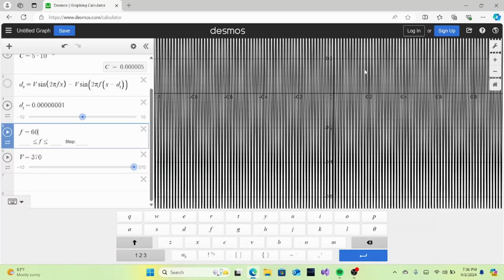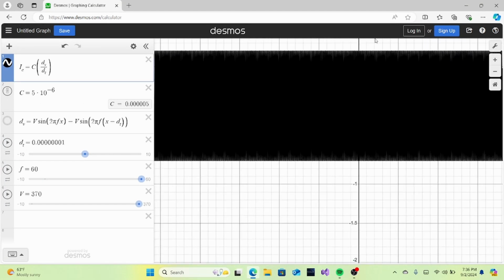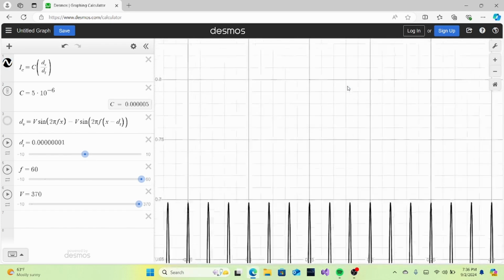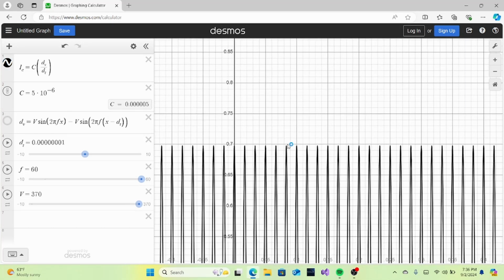But if we go up here, we could expect to see about 0.7 amps of current being drawn. And you can see here it comes up just a little bit short. Most of the time when I look at the start winding current of a condenser fan motor and I see that it's about 0.68 amps, 0.69 amps, I know that the capacitor is likely okay. I still check it just to be safe, because if it's drawing 0.68 amps and it has 400 volts or more across it, that can indicate that the capacitor has lost capacitance and it's on its way out. You need to replace it. But likewise, this is basically the way that you would do that.